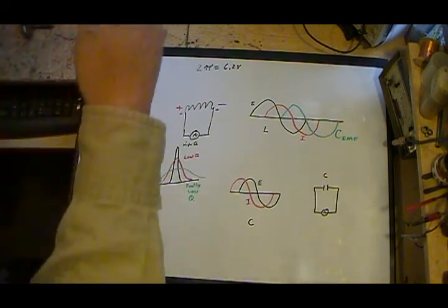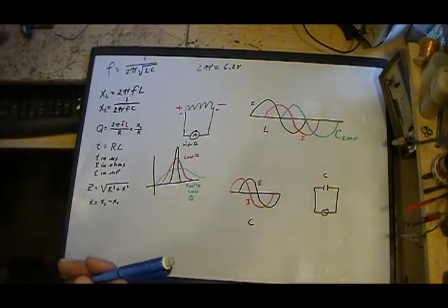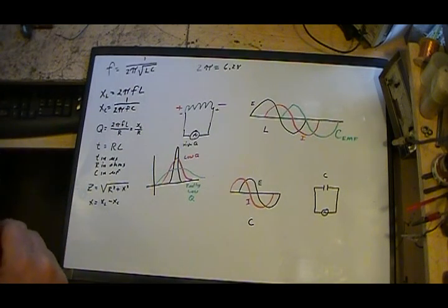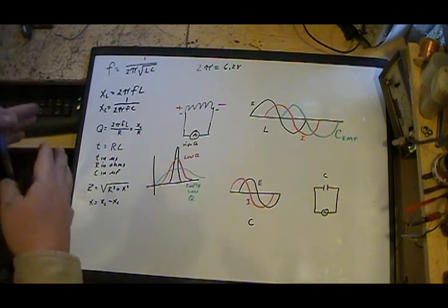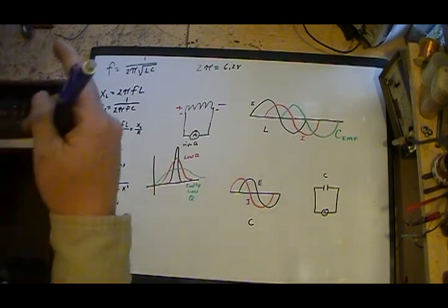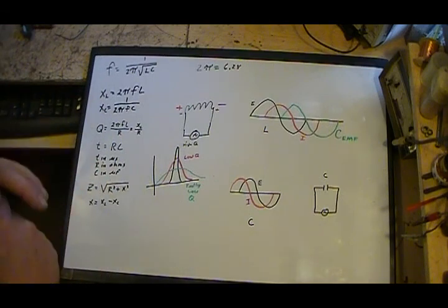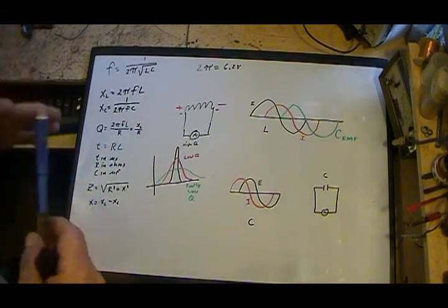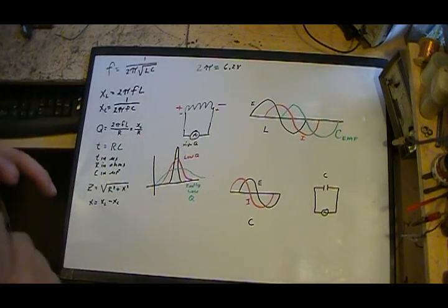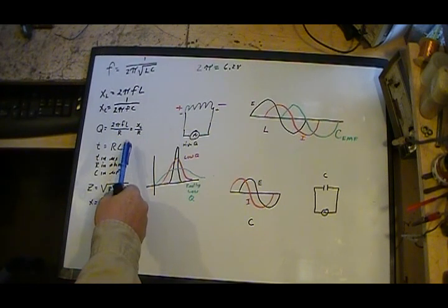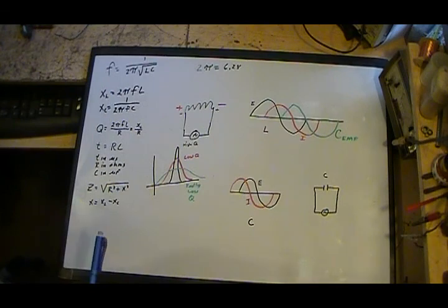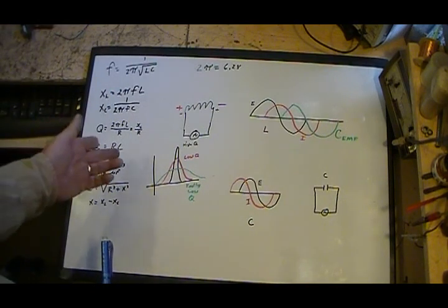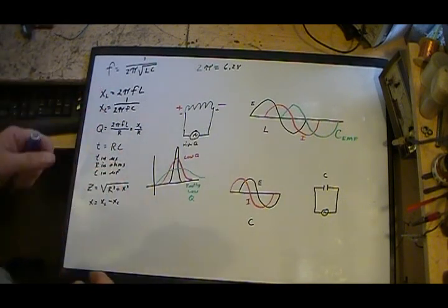So if you start changing out that capacitor, say it had a 0.05 in there, and you decide, well, the only thing I've got is a 0.2, and you throw it in there, it's going to drastically change that time constant, which is going to have a drastic effect on how the radio and the AVC circuit work. So it is an important formula to keep in your head, and it's reasonably simple. T equals RC.